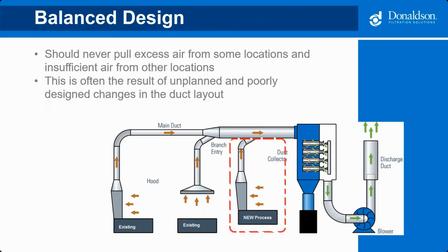And it's really common, we see it quite often, where customers will add drops to an existing system without even considering the impact it has on the existing equipment that they're venting. So in most cases, these systems aren't modified to accommodate the additional airflow or static, and then it becomes out of balance.